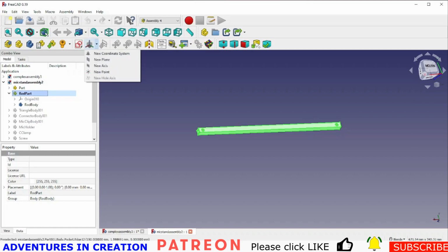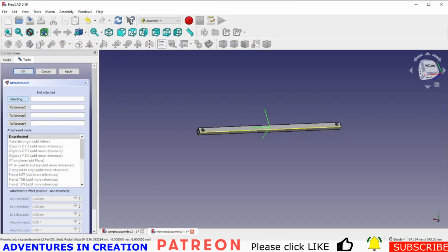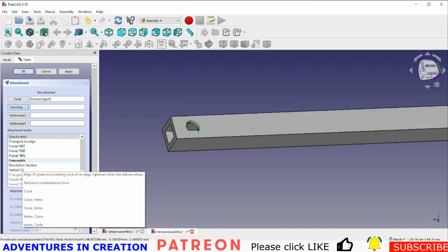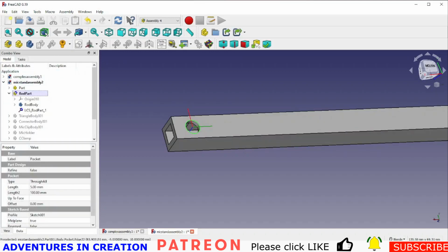LCSs. So I'm just going to create a new LCS, and I'm going to call it LCS rod part 1. Say OK, and then I'll zoom in so you can see, I'm just going to pick this concentric circle, and I'm going to say concentric, and apply that, and now you can see there's an LCS in that hole. So we're going to use that for our assembly.